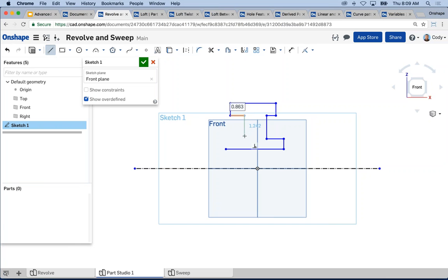You're taking that slice of the part or the sketch and rotating it to create a round part. Now, another tip that I have is, as you're sketching like this, one thing that you may run into is, I need to constrain the end of this line to the end point down here. But you'll notice it's not appearing as I drag that line back and forth. I need that reference to the point below. So what I can do is mouse over that point, then move my cursor up, and you can see now it will wake up that reference.